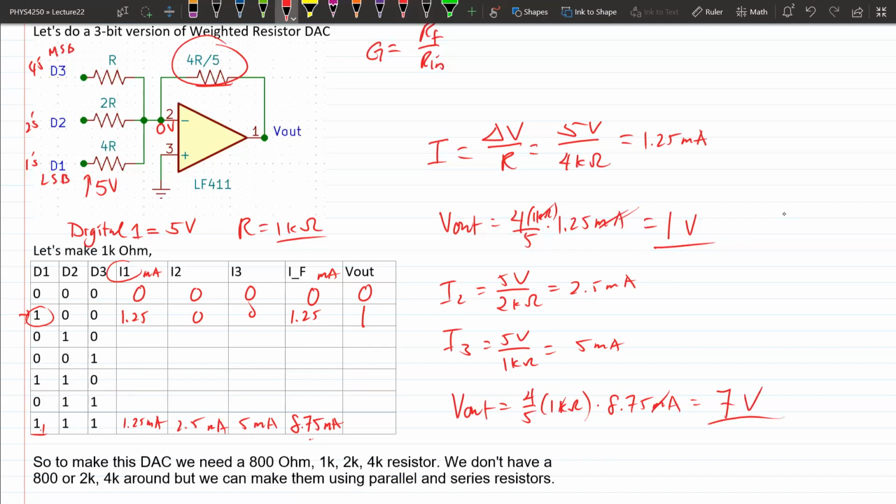Okay. Hopefully this circuit makes sense. I know it's been a while since we dealt with op amps, but there's only 2 rules you need to know about op amps: the input terminals have to be at the same voltage, and there's no current going into them.